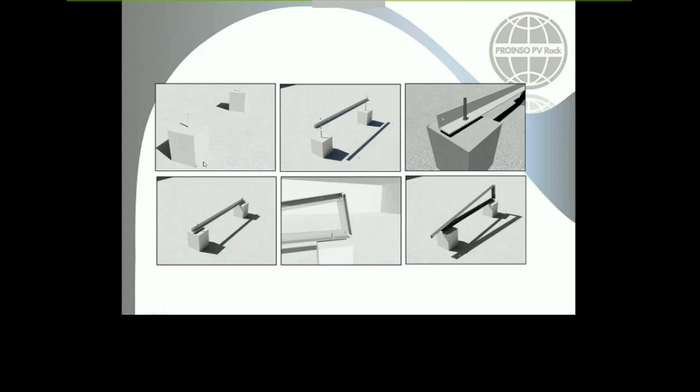In this case, you have to do the civil works that the concrete involves previous to the installation, with the dimensions that a local engineer will give you. We always have some advice on the dimensions, but it's better to always double check with a local engineer. And you will have a piece of your hanger bolt that goes above the concrete surface.